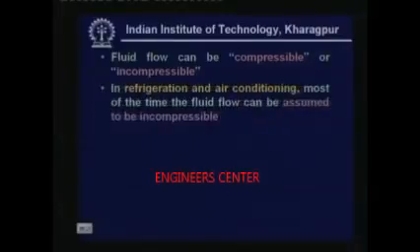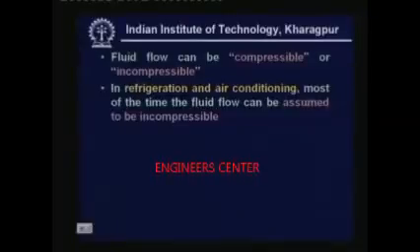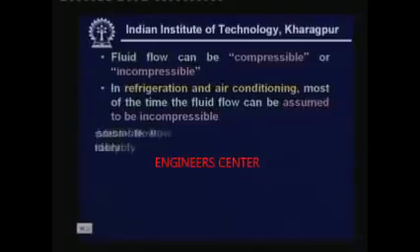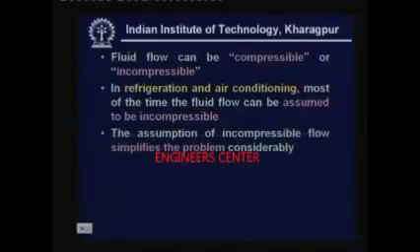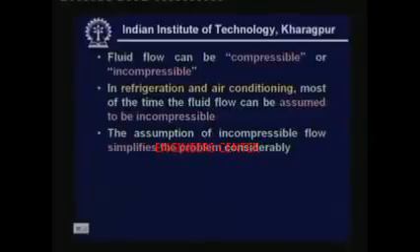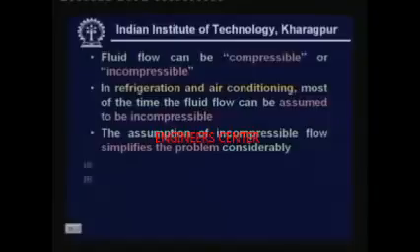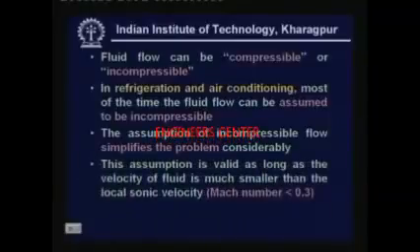In most of the refrigeration and air conditioning applications, the fluid flows can be assumed to be incompressible. Why do we assume this? Because this will simplify the problem considerably. So, most of the times we assume the flow to be incompressible and the resulting mathematics will be simpler. However, you cannot just like that apply the assumption of incompressible flow everywhere. You have to see its validity.